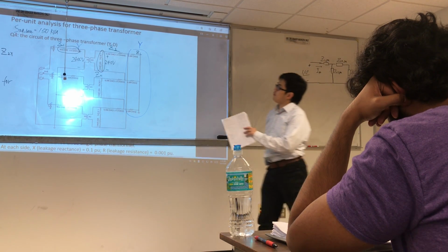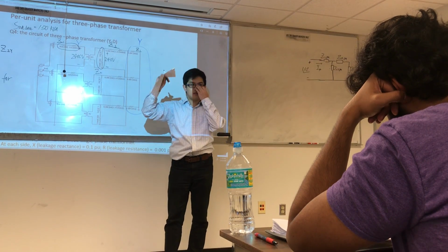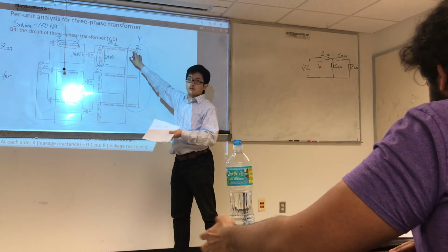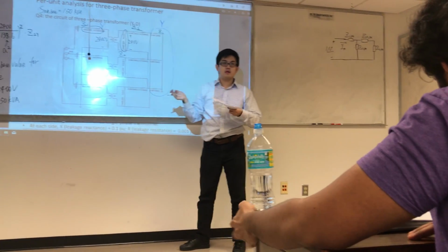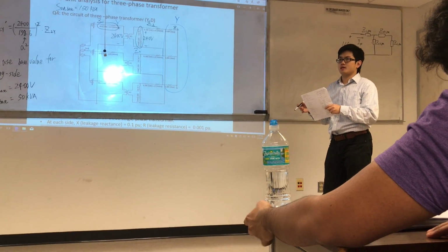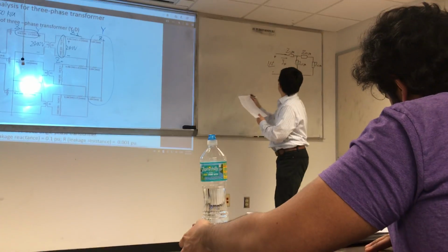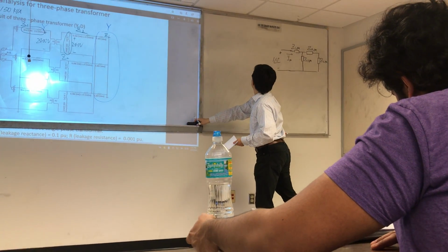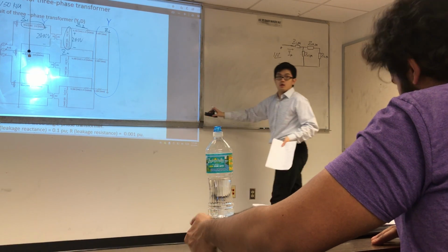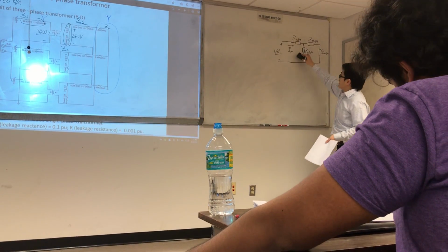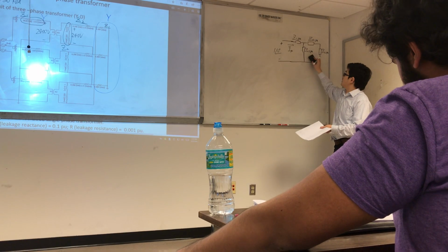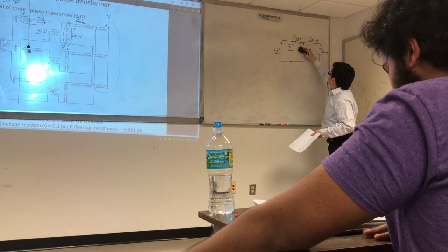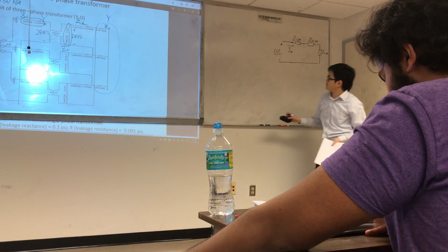Okay, so in your question 4, you still have another small question to find the maximum value. You need to change the load, then find the maximum value. This is named impedance match. So how to do that? Let me remove this middle part, because this one is much larger than these two, so we can ignore it. So your circuit is like this.